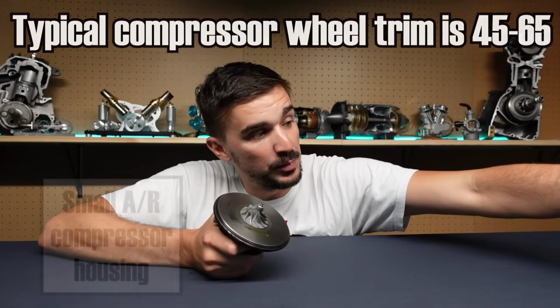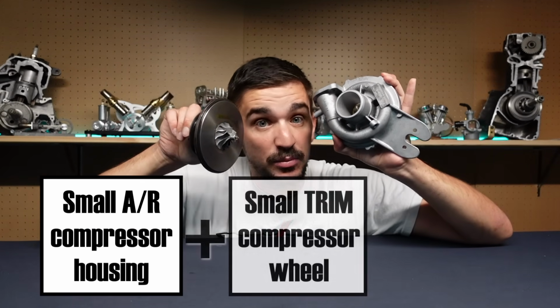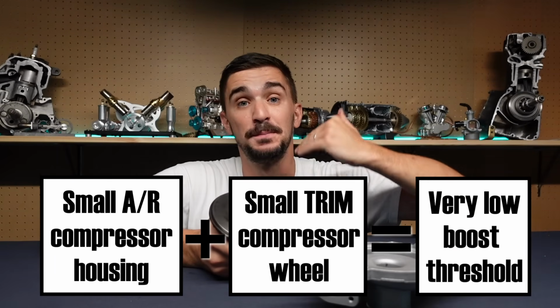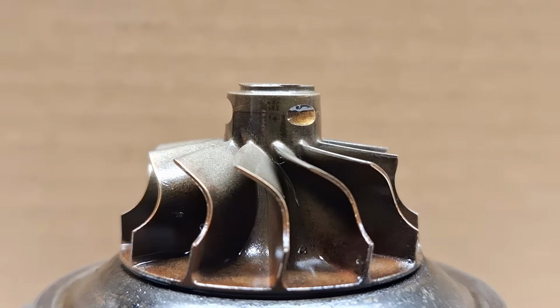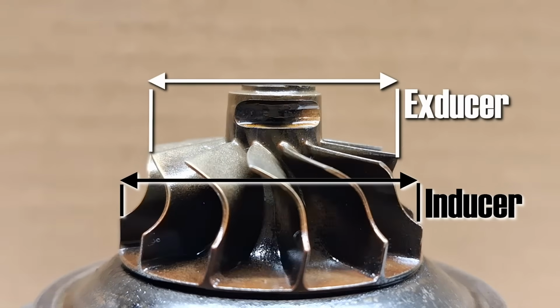So if you take a compressor housing with a small A over R and combine it with a compressor wheel with a small trim, you can expect to have a very low boost threshold, or to build peak boost at very low RPM. Now, the trim for the turbine wheel is calculated using the same formula, but remember that for the turbine wheel, the inducer is the larger diameter and the exducer is the smaller diameter.